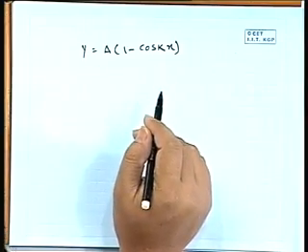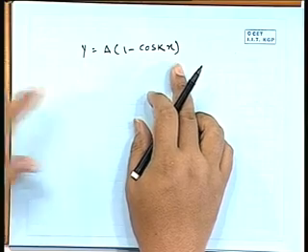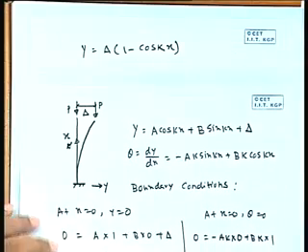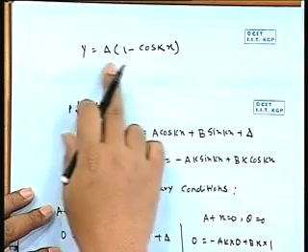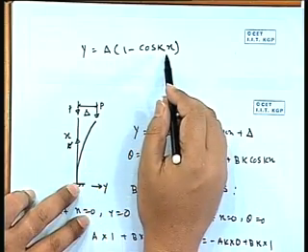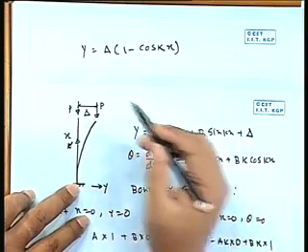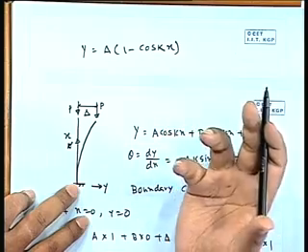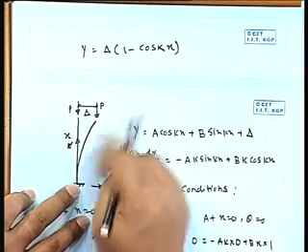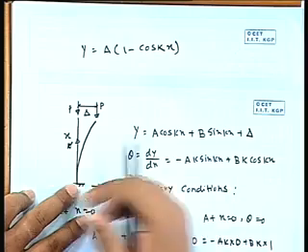Now, this is the equation of our deflected shape of the cantilever. So, the shape we have drawn, this is the equation, right. So, y equal to delta into 1 minus cos kx. It will start from 0 and gradually it will be equal to delta, and in between it will follow a cos curve. Now, delta is any arbitrary value. We can give here 1 millimeter deflection or 5 millimeter deflection. Based on that, it will take that particular form. So, the whole thing is multiplied by delta. That is basically the shape of the curve.